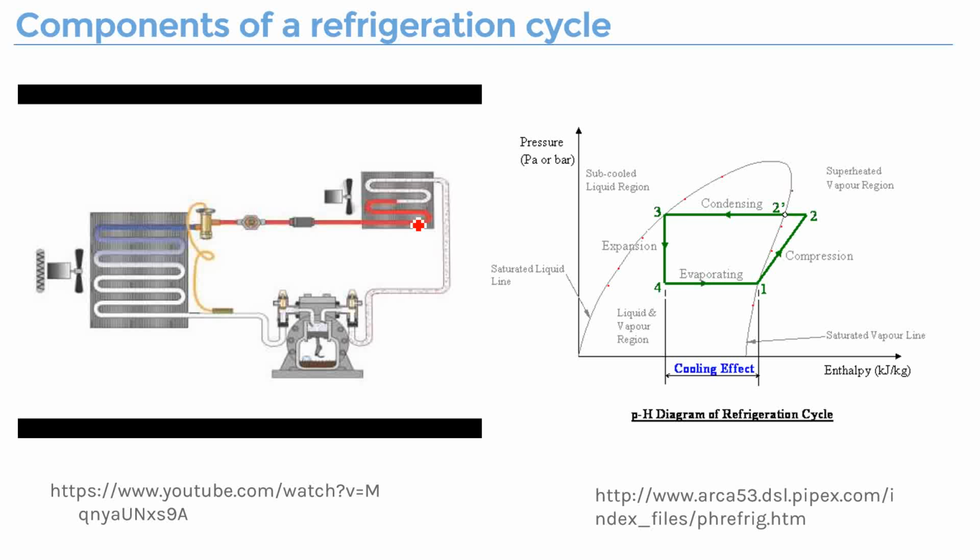But that amount of energy you absorb is similar here. You need to release some heat to have the vapor change state to liquid, or in the evaporator to change the phase. And that, maybe in thermodynamics, is called sensible heat and latent heat. For sensible heat, you have an observable temperature change.